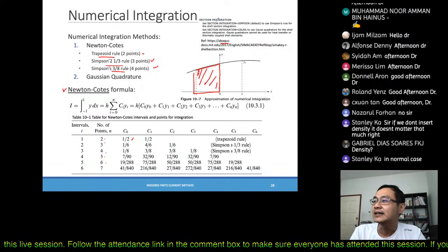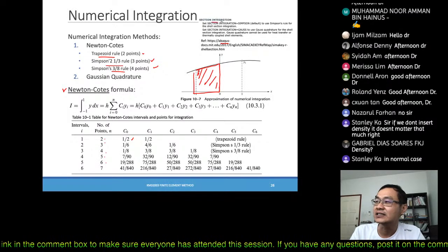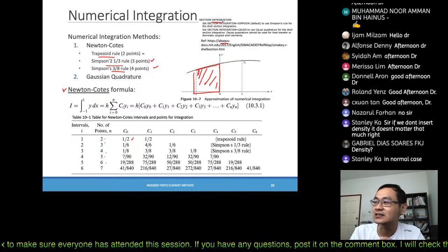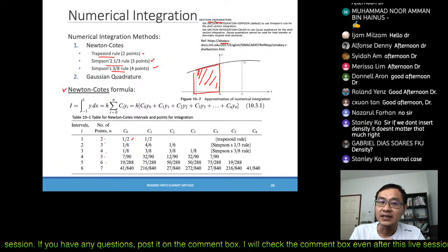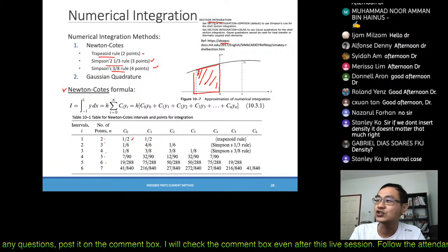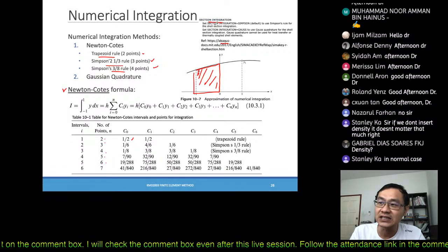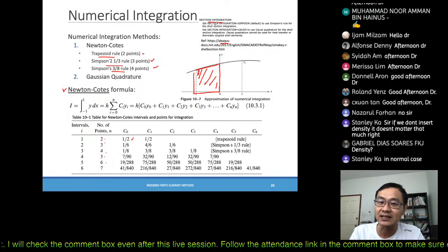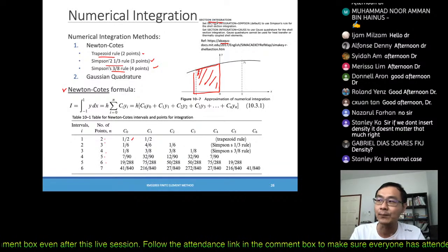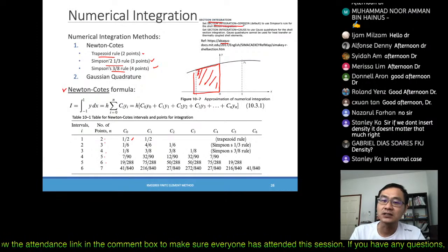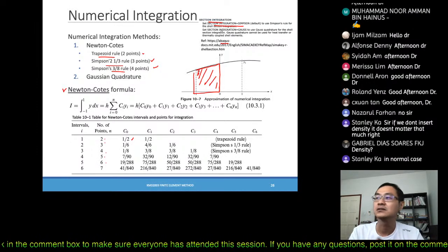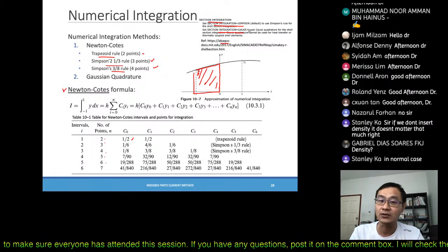In the section you can search, for example, for section integration. In software like Abaqus, you can actually set which numerical integration method you want them to apply, by adding a code like section integration equals Simpson, or section integration equals Gauss.